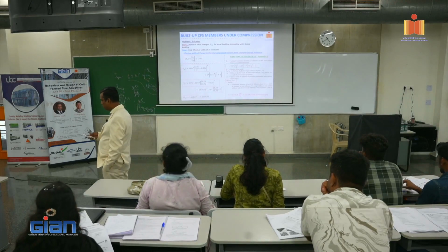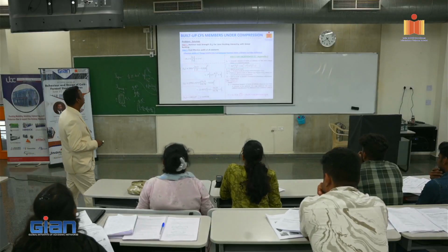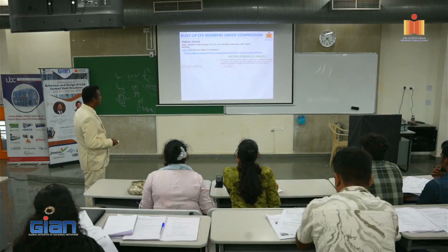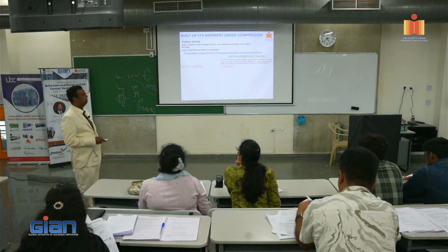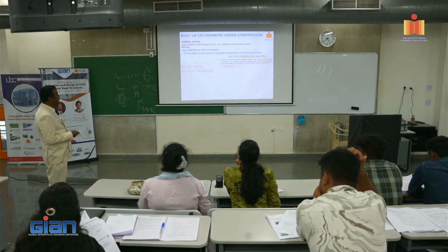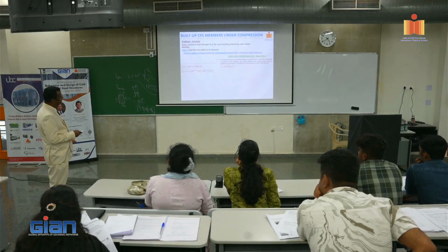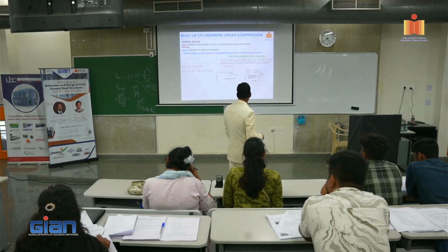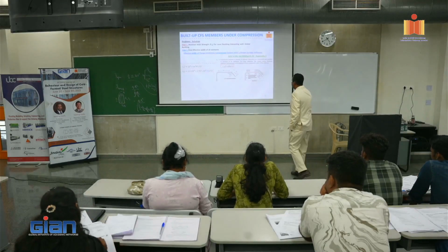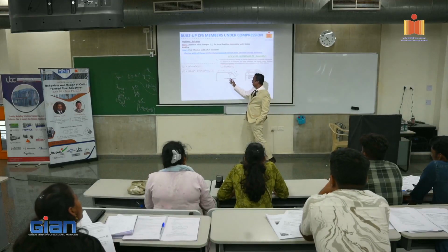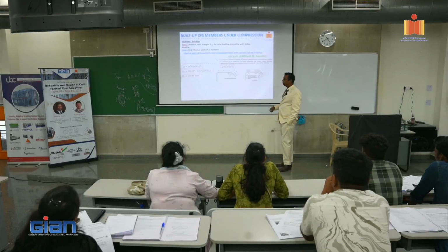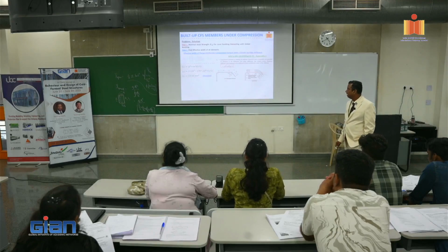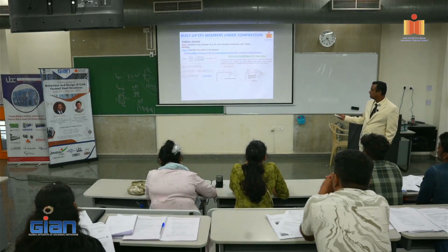But we cannot come to that conclusion because we have to calculate Is. Is provided is given by d cubed t sine squared theta divided by 12. Here d is 11.04, the depth of the lip, cubed, into the thickness 1.957. Sine squared theta is sine squared 90 because it is actually 90 degrees. Divided by 12, when we do so, this is the value that we get. It is also used for some 45 degree stiffeners, in which case you can put the angle, but in our case it is 90 degrees. So we get Is equal to 219.77 millimeter to the fourth, which is much less than 1465. Ri is 0.149, less than 1.